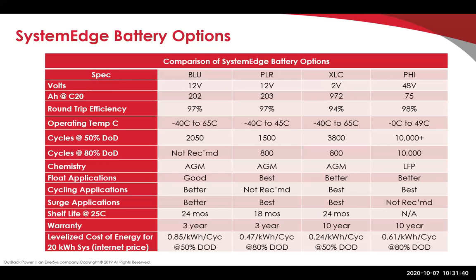So it's not saying you have to use lithium ion batteries, but I would check with your local jurisdiction and find out what their interpretation is, because that's all that matters. They are kings of their own fiefdoms there. But it's my understanding that the batteries are listed UL 1973, and you're using them with the UL 1741 inverter, so there shouldn't be a problem. We just didn't do the testing to UL 9540.